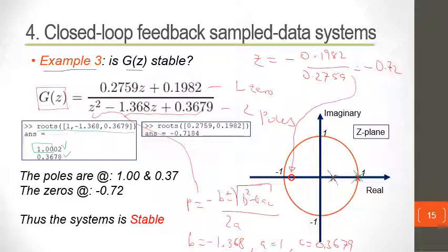And so you can approximate your poles, and you can approximate your zeros. Your zero can be approximated this way as well, by just typing roots, looking for the roots of that polynomial. And because here, with a fairly robust approximation, we see that one of the poles is within, the other is right inside. So although marginally stable, the system is stable. The system can be said to be stable in this instance.